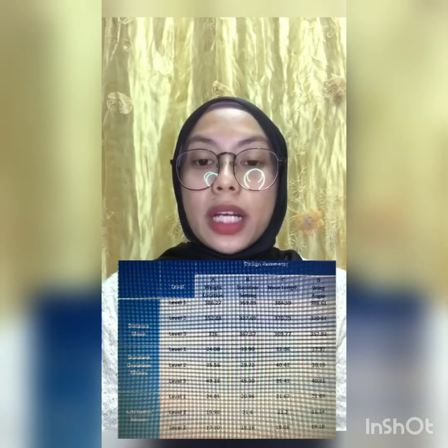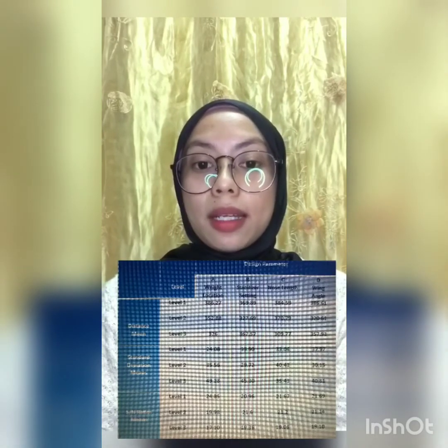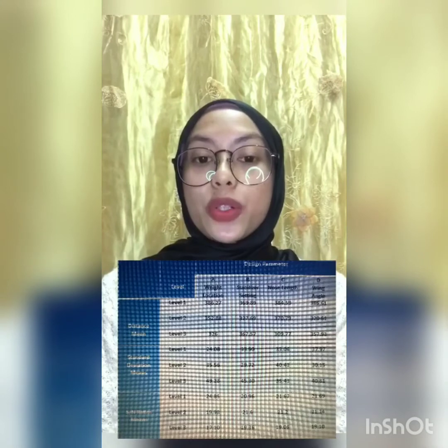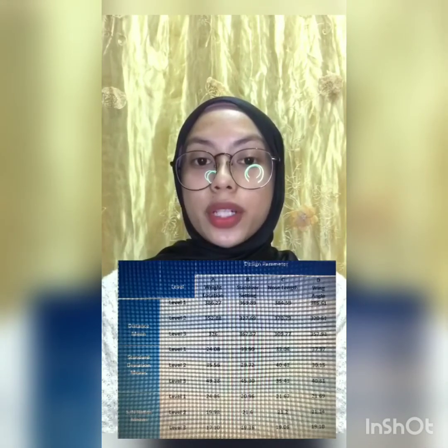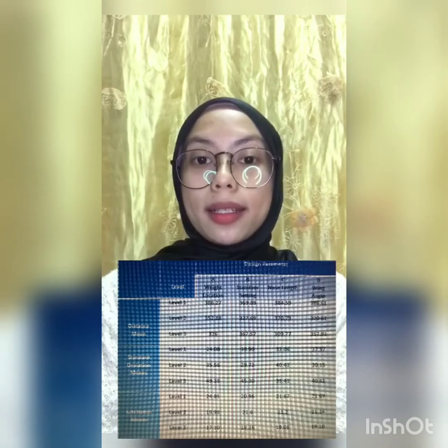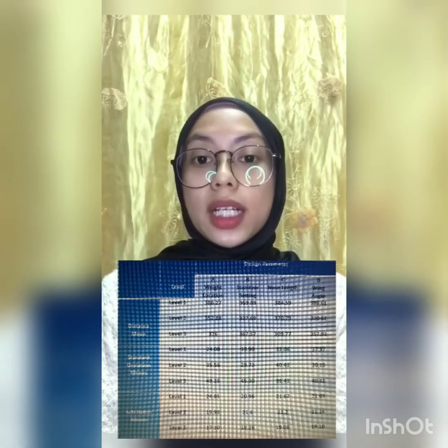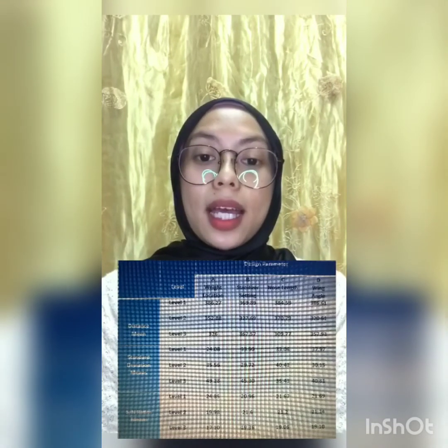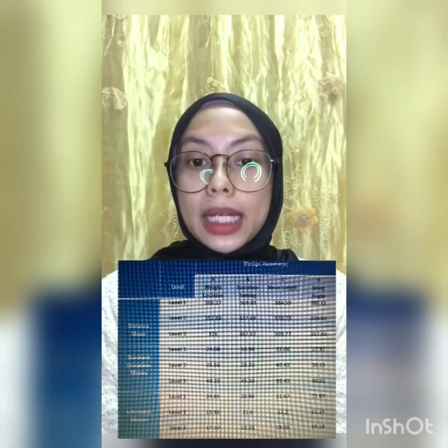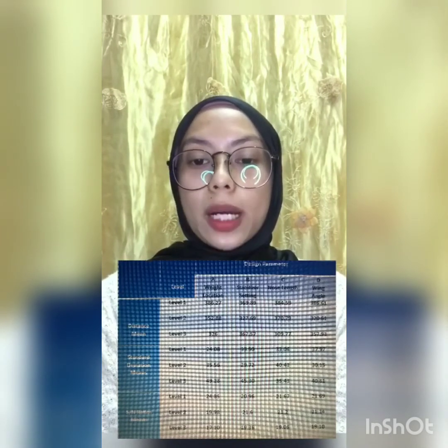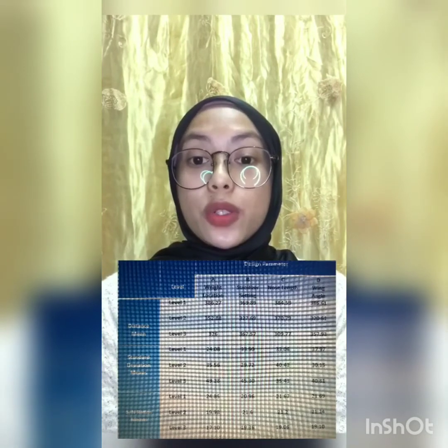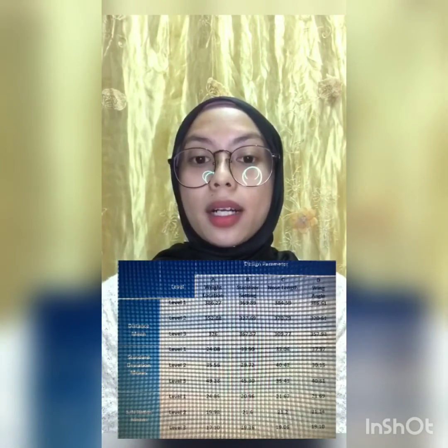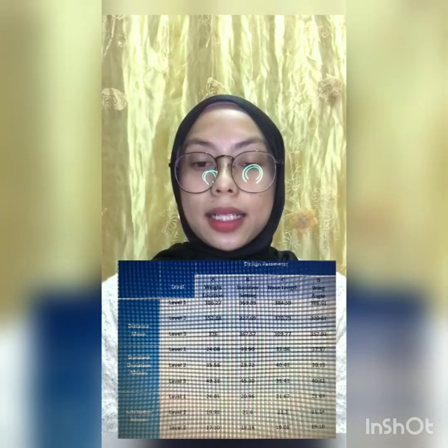The number of levels that parameters should be varied at must be specified. For instance, a stabilizer setting might be varied to a low and high value of 309.77 and 386.61. Increasing the number of levels to vary a parameter increases the number of experiments to be conducted. If the difference between the minimum and maximum value of a parameter is large, the values being tested can be further apart, or more values tested can be closer together.